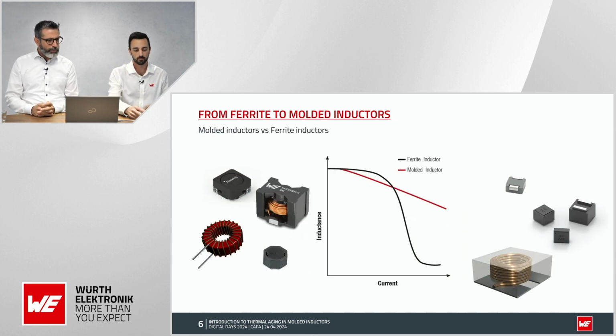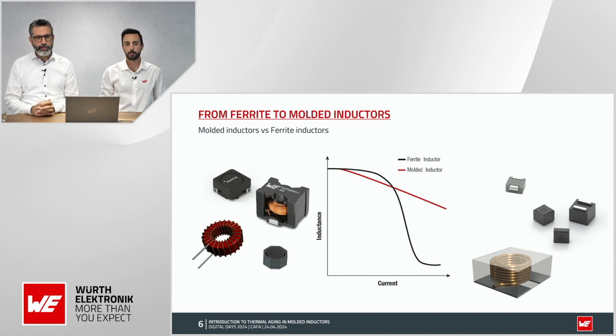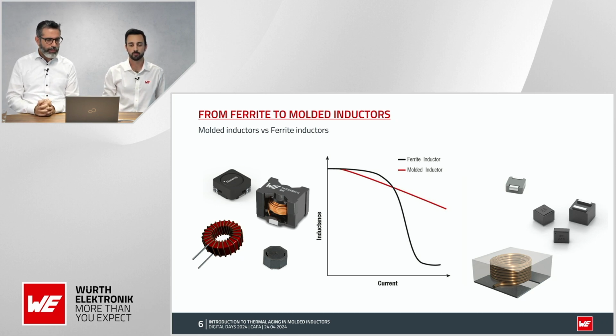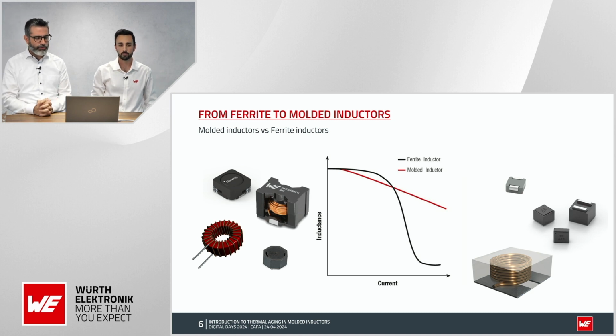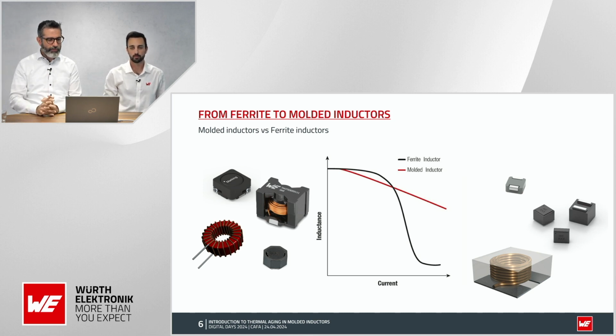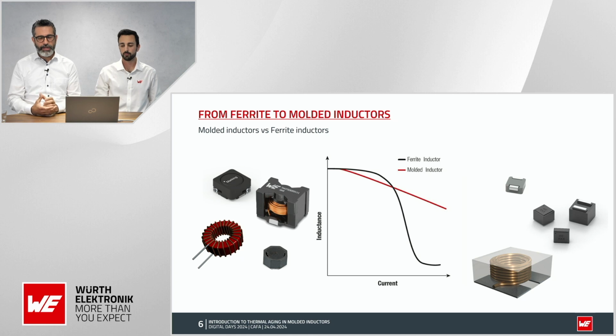Thanks, Carlos. So ferrites are always a very good option, and they perform very well in high frequency applications where the frequency is going into a high domain. Then, talking about saturation behavior, ferrites also have good saturation behavior, maintaining constant inductance until reaching one point, the saturation point, where the inductance drops off very sharply. So it is called a hard saturation.